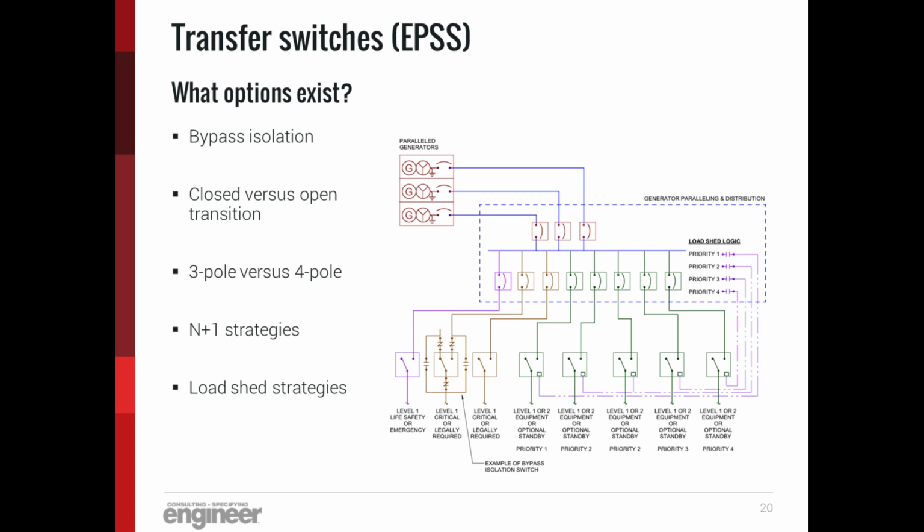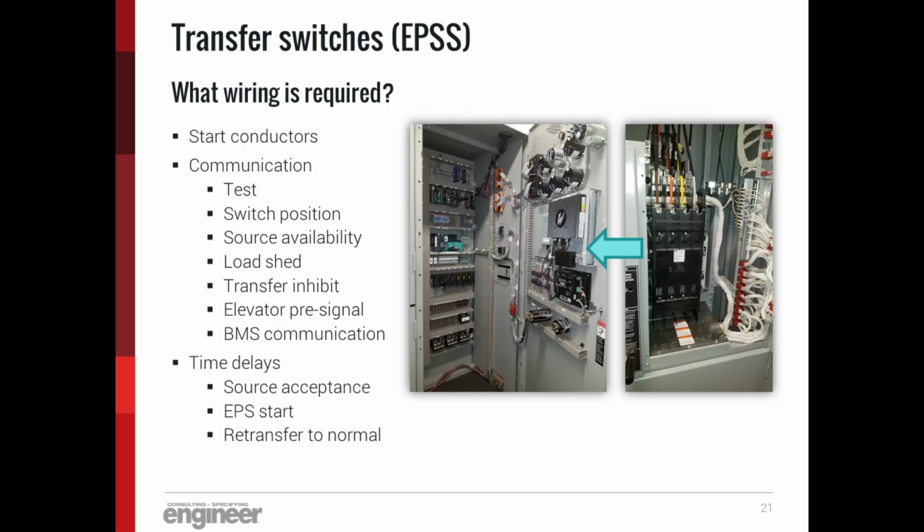And that's going to be cabling as well. Now, ATSs or transfer switches have a variety of cabling requirements to them. Keep in mind, 2017 NEC says that we now have to monitor the integrity of the start conductors. And doing that might actually add a third conductor. So if you're complying with 2017 NEC, because maybe you have multiple things to comply with, not just CMS, but maybe also a local jurisdiction, and they want to see that third conductor, you have to plan for it, as well as any fire rating or 2-hour rated protection that those conductors might have.